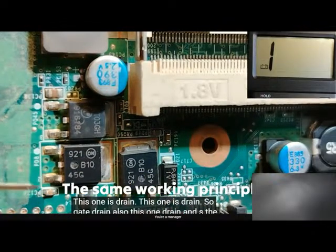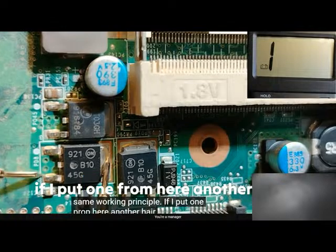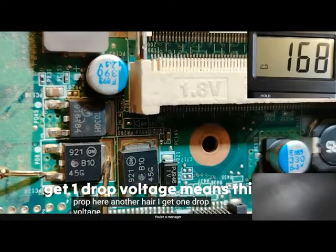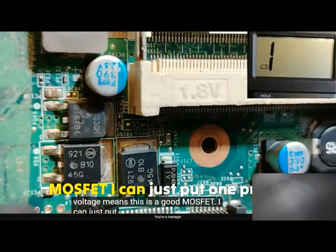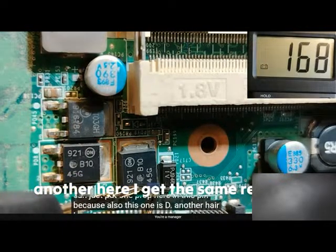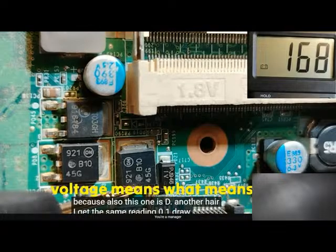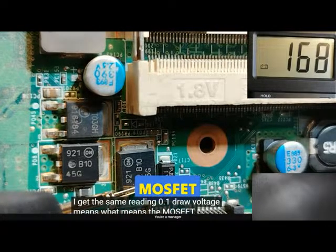The same working principle. If I put one probe here, another here, I get 0.1 drop voltage. Means this is a good MOSFET. I can just put one probe on this pin, because this one is also drain, and another here, I get the same reading, 0.1 voltage. Means what? Means the MOSFET is serviceable.